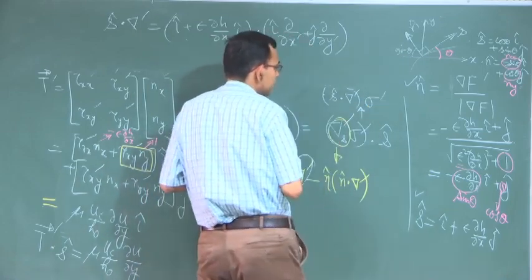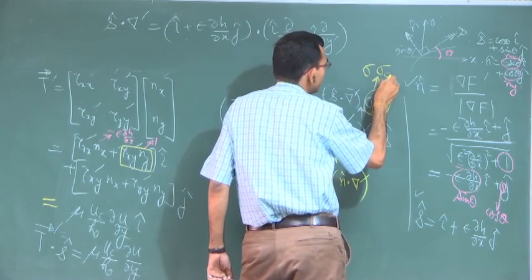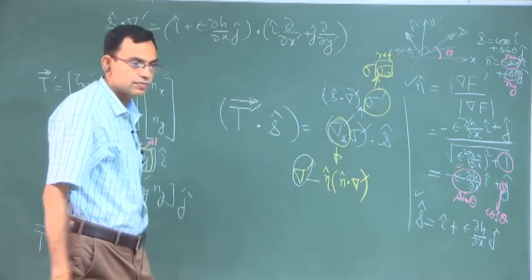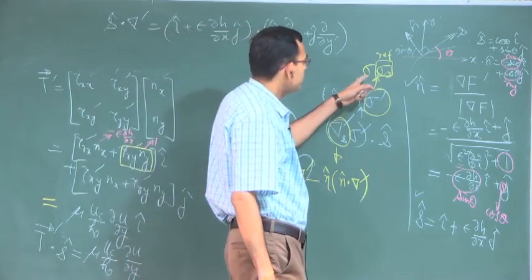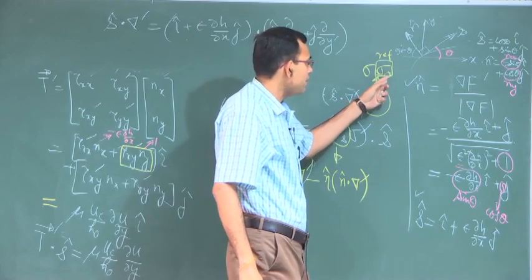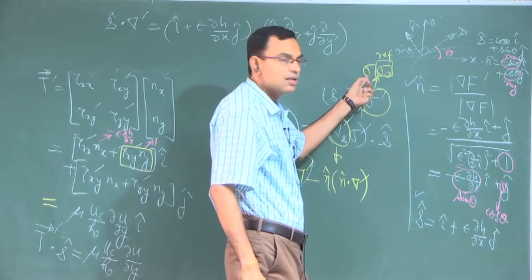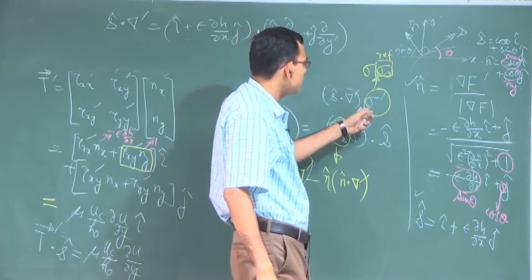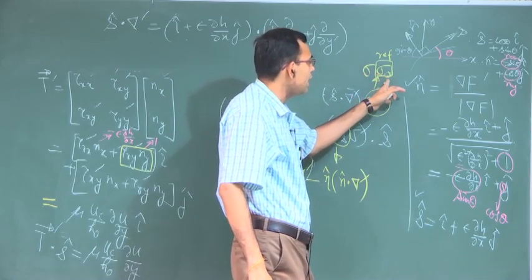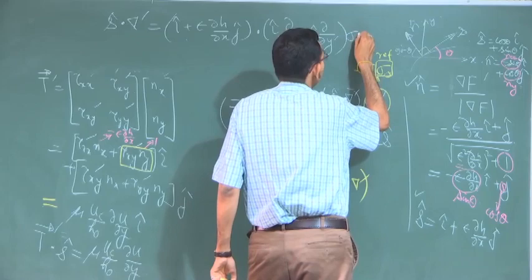You can write sigma dash as sigma into sigma 0, where sigma 0 is the reference surface tension coefficient. So, that makes sigma a non-dimensional surface tension. This is a dimensional reference surface tension parameter, and therefore, this is a non-dimensional surface tension. In this way we are transforming a dimensional surface tension to a non-dimensional surface tension sigma via a reference sigma naught.